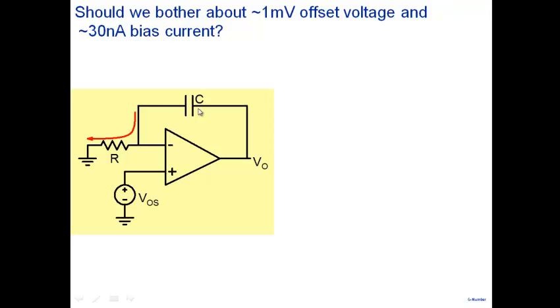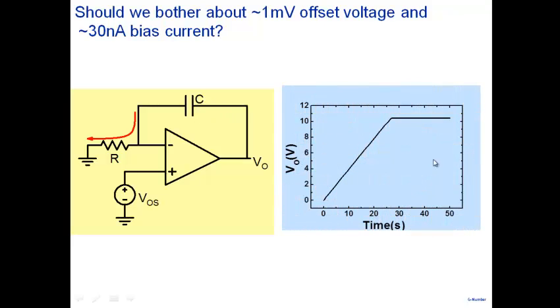It will start charging. And this is what you will see here. Even if you're not applying any input, the capacitor will start charging, and it keeps on charging. Eventually the value saturates, because you know that the op-amp output will not go beyond the supply voltage. So it saturates at this point. A very small voltage here will saturate your op-amp. So you are somewhere here.